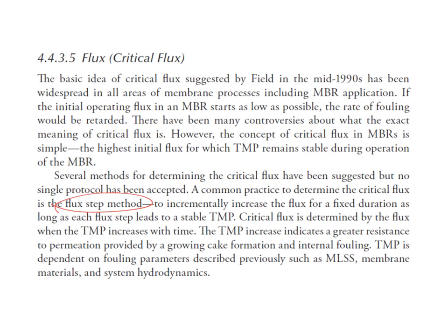So TMP increase indicates greater resistance to permeation provided by a growing cake formation and internal fouling. So the TMP is dependent on fouling parameters described previously, such as MLSS, membrane materials, and system hydrodynamics.